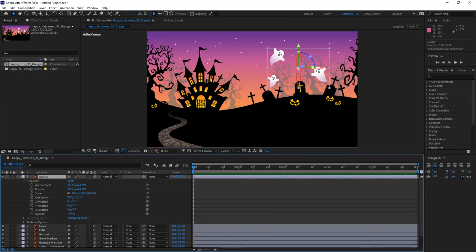So if I'm working on the, not vertices, axis, sorry. So if I'm working on the x-axis, you'll notice that I can rotate based on the x-axis when I roll over that rotation circle. Or if I roll over the blue one, that's the z-axis rotation. And you will notice that the arrows indicate the edge in which the actual rotation occurs.